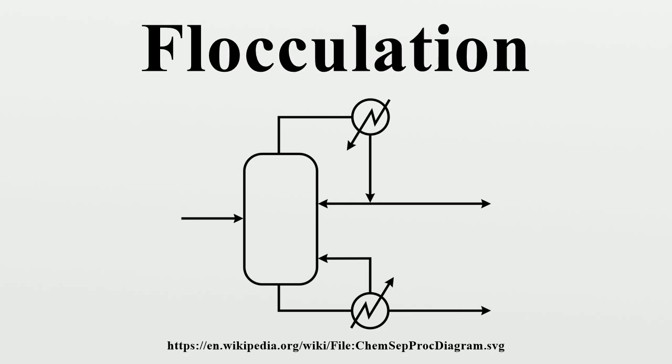During flocculation, gentle mixing accelerates the rate of particle collision, and the destabilized particles are further aggregated and enmeshed into larger precipitates. Flocculation is affected by several parameters, including mixing speed, mixing intensity, and mixing time. The product of the mixing intensity and mixing time is used to describe flocculation processes.